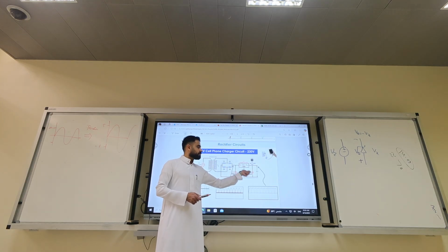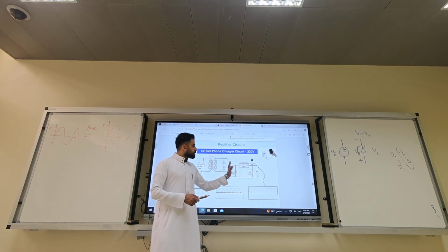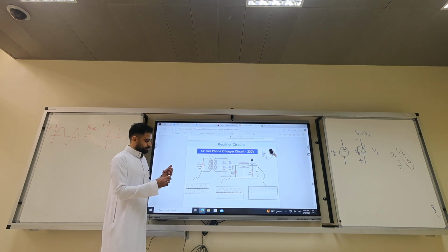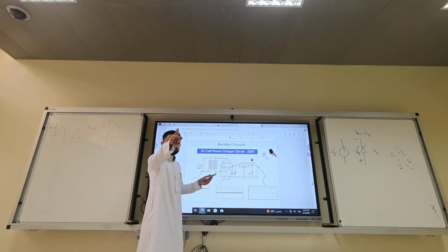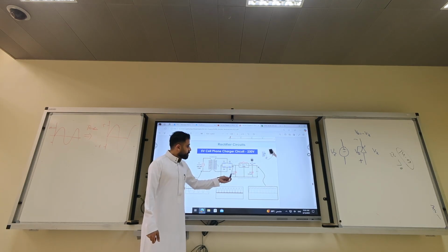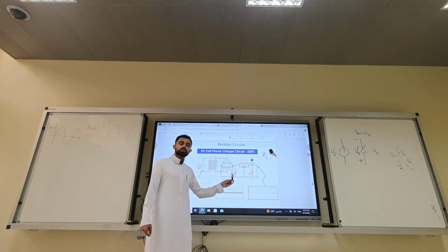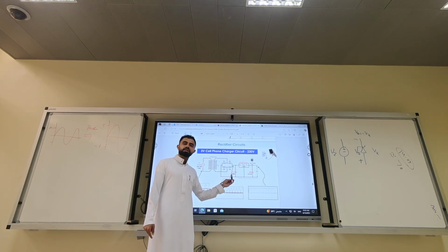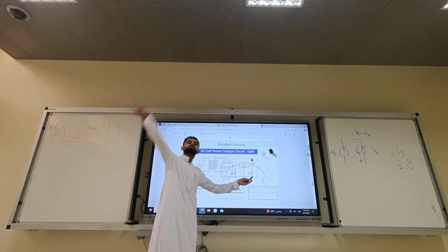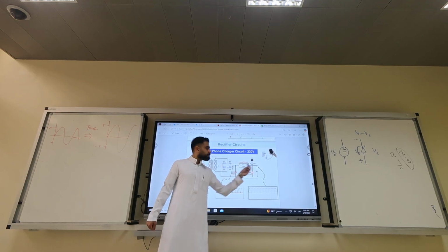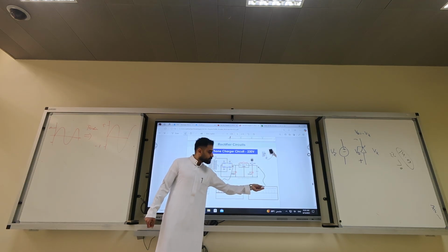This capacitor could be another smoothing, it could be filtering, I don't know. But what I want you to know is this capacitor is smoothing. Note that this is 1000 microfarad, this is 0.01 microfarad. So this one is much larger. So which one do you think is the smoothing? The first one. But this is a voltage regulator, it could have a Zener inside. This is to improve the quality. But up until here, this is the output you can get.